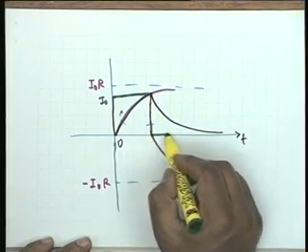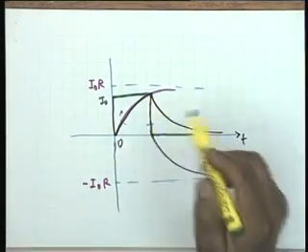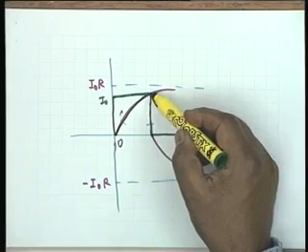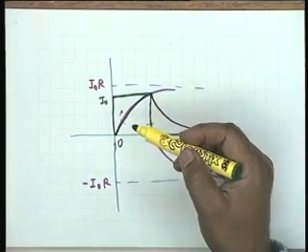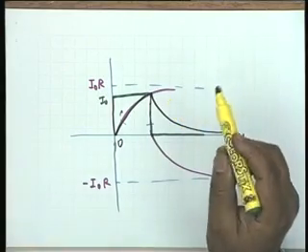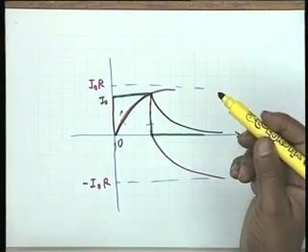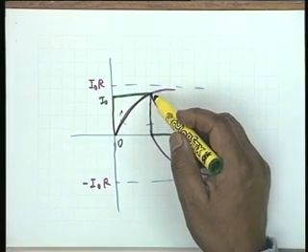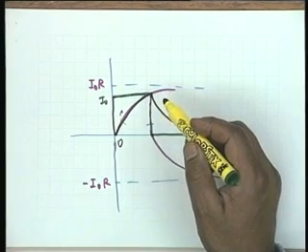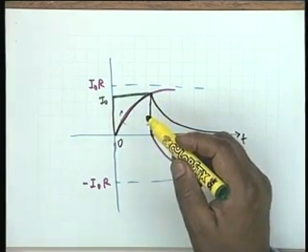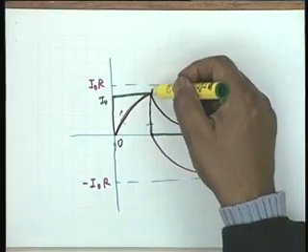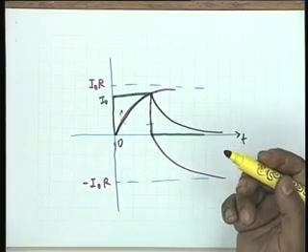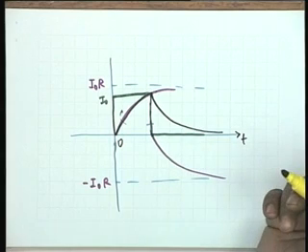I0, this was the excitation, and as long as the excitation is there, you notice that the voltage rises exponentially. As soon as the excitation is taken off, now comes the physical concept. What happens? Excitation taken off, the capacitor has charged to less than I0 r, and then it discharges. The excitation is drawn away, so the capacitor charge gradually discharges, and this is why this exponential decay. Ultimately, when you allow sufficient time, the capacitor discharges completely and the voltage across it becomes 0.